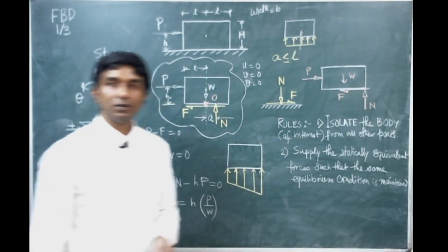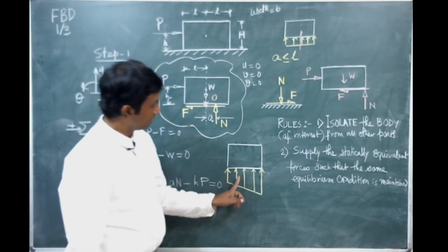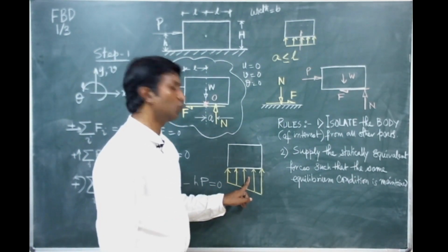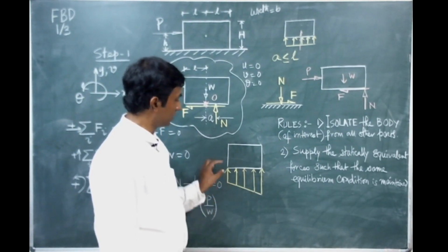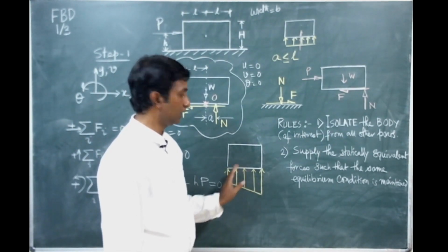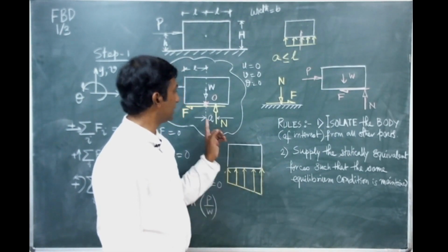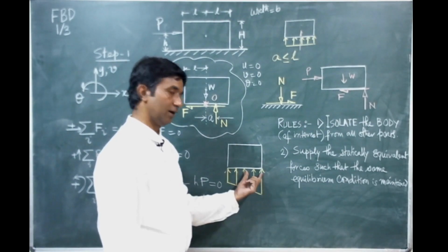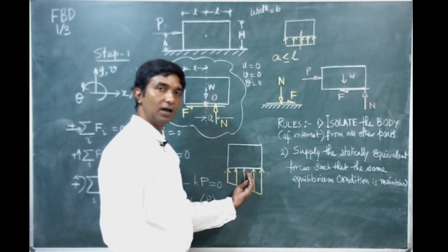Okay, so you see when the resultant from this trapezoidal distribution, you can just work out the geometry. Even if you consider this value 0, you get a triangular. Then also you see that small a cannot be L, small l. Okay, it is always less than small l.